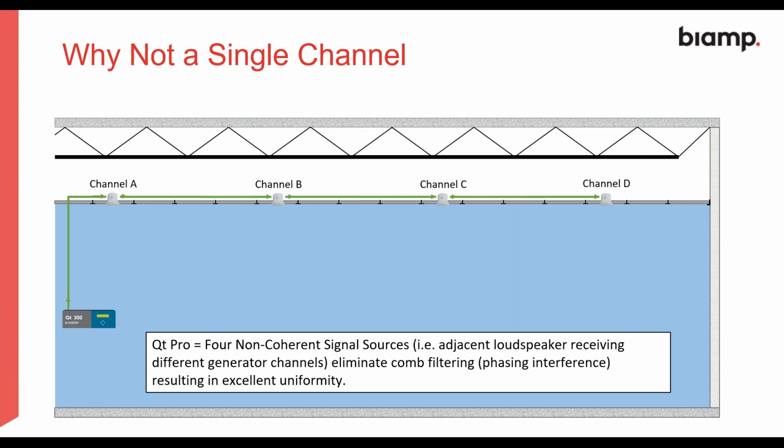Just at this point, I'll take a couple of questions that are relevant. How do we address deployment that requires more than 6 zones? To do that, we would quite simply have another 6-zone controller or a 3-zone controller. And there is a second question. Is there a same for the partition that goes all the way up to the soffit? That's from Robert. We treat the ceiling height as a ceiling height. So whatever's going above the ceiling does not matter in the direct field. We're only concerned with the area below the ceiling.